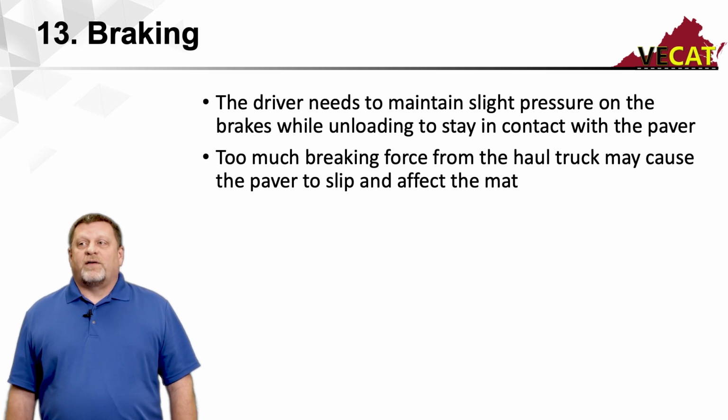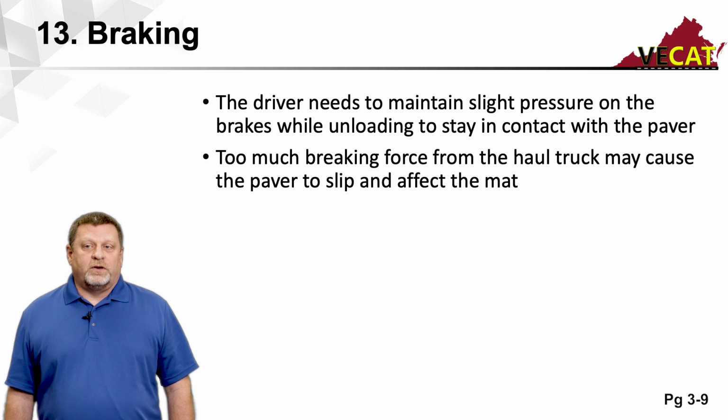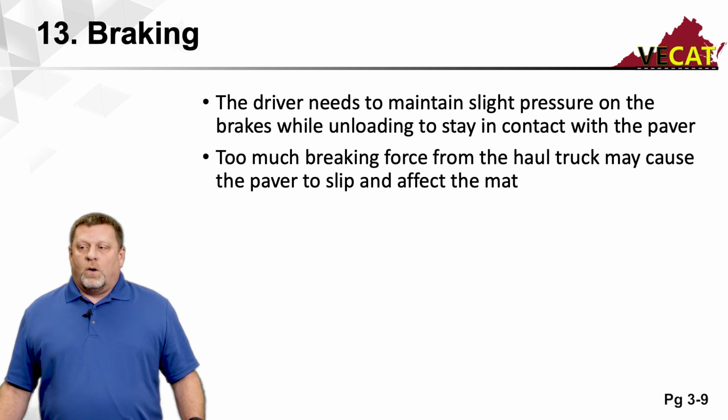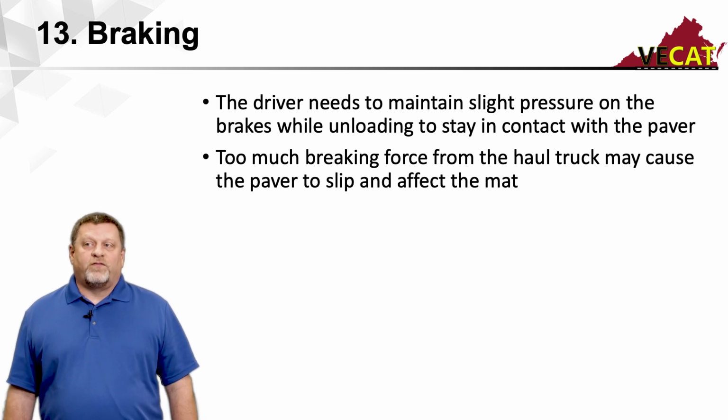Again, braking. The driver needs to maintain a slight pressure. He doesn't want to have so much force on the brakes that the paver will begin to jump or even hesitate to go forward because of too much pressure being applied by the truck brakes. But he wants to maintain this pressure just enough that they'll stay in contact until the full load has been emptied.